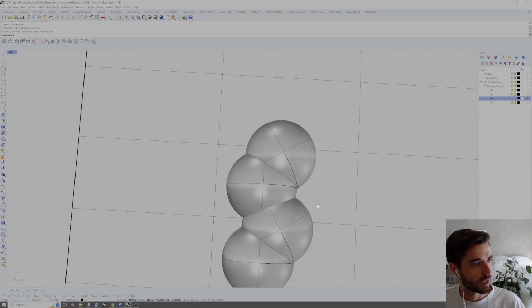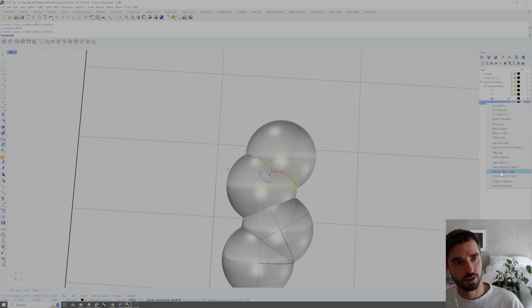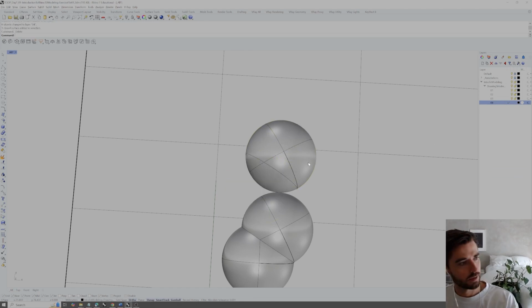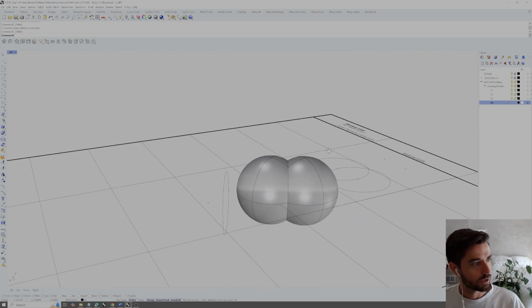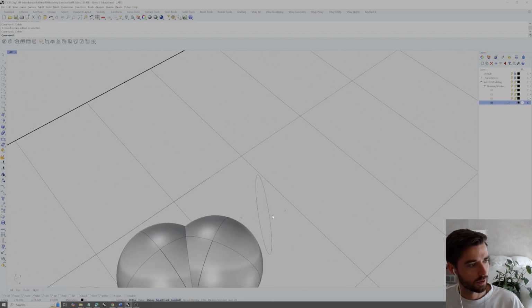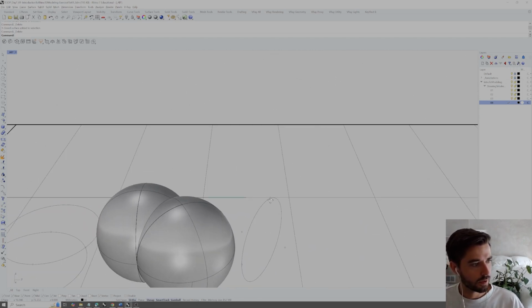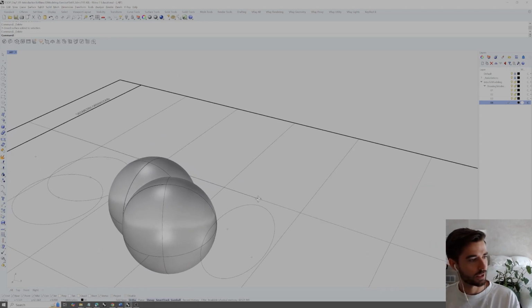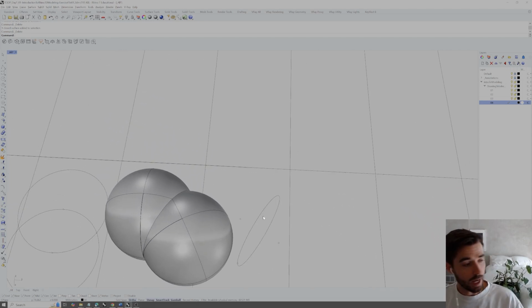I'll fix this by maybe scaling them down for your base file. But in this next step, if we wanted to select those last things we just moved, we can type SELL, select last. It selects everything we just moved, and we can go ahead and change that layer to step 4, double click to make that our current layer, and we can delete each of those spheres.